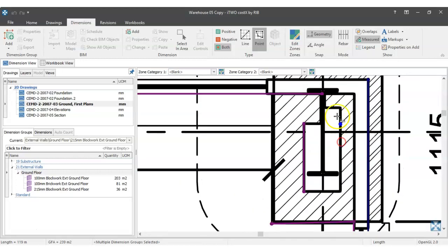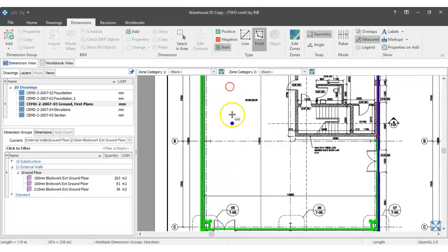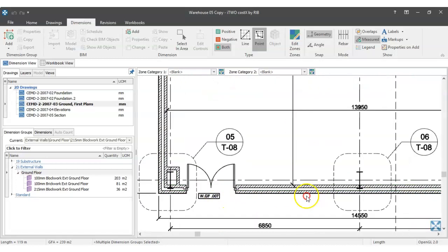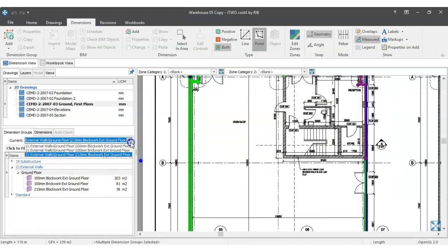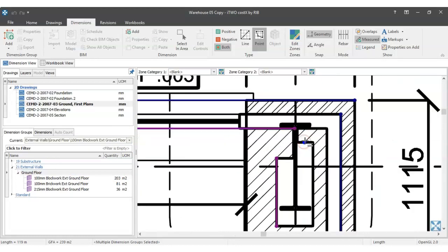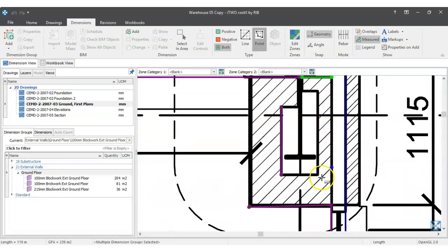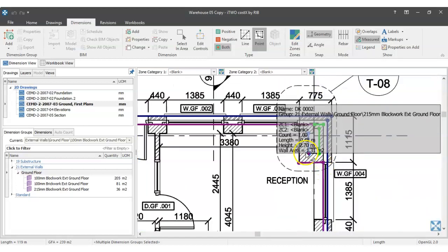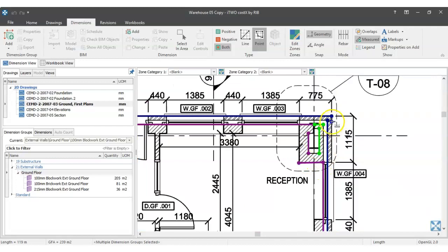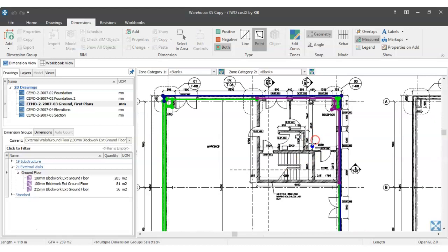And I can see that little bit of 100mm block I haven't measured. And everything from the external walls perspective on the ground floor, I'm scrolling around just to see, I have covered. So that was the 100mm block. So drop down, click the item. You may have to go back and measure something that you missed. And from there to there, and then this little bit from there to there. So you can see, from a takeoff perspective, how things are joining up. And I'm not double measuring corners. I'm not over measuring items.